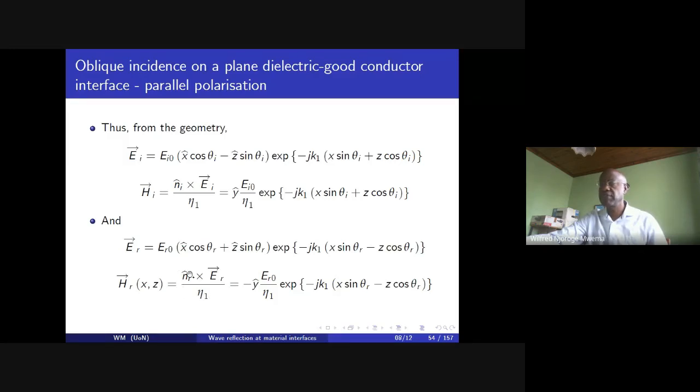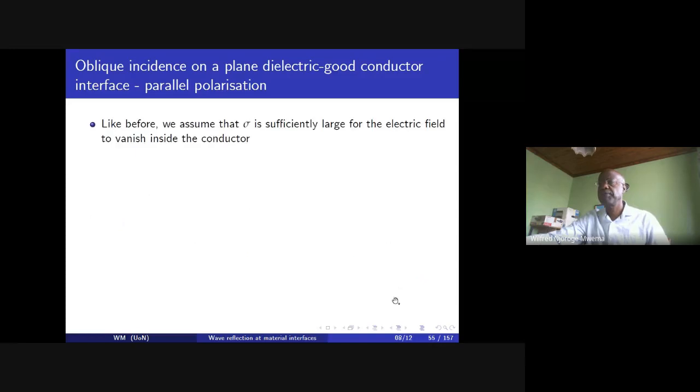That is the direction vector cross the electric field intensity vector, divided by the wave impedance. If you are given the H, all you have to remember is that you can multiply that by the impedance, and then take the cross product with respect to the direction vector and then expand. And you'll find that you'll always get the one from the other for TEM waves, so to speak.